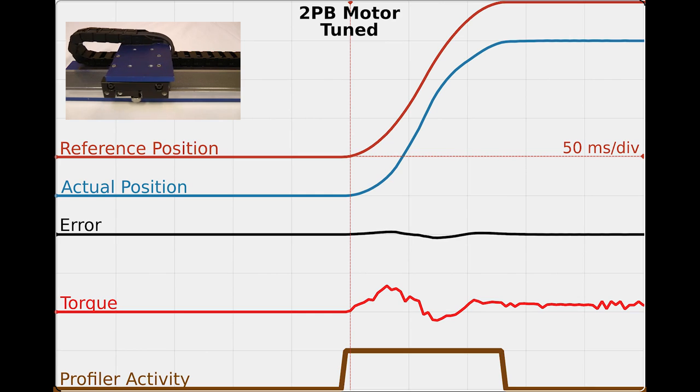As the motor moves back and forth, we can see that the position error throughout the move remains very low, close to 2 counts. The motor's total move time is also less than that of closed-loop microstepping. The motor settles here within 4 milliseconds rather than 21 milliseconds.